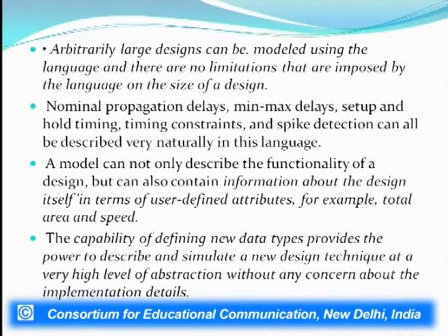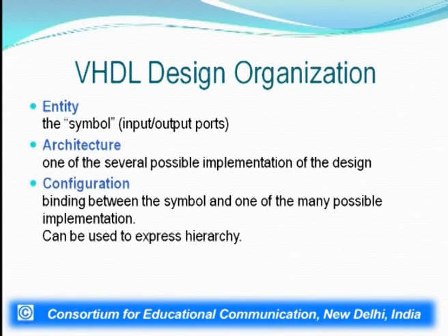Now, the capability of defining new data types is a very important feature of VHDL, wherein a user can introduce his or her own defined data type into the language, and that can also be supported and can be used to simulate a design technique at a very high level of abstraction without any concern about the implementation details.